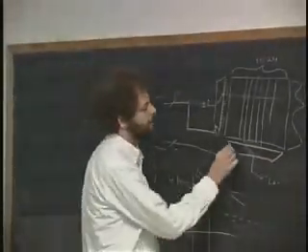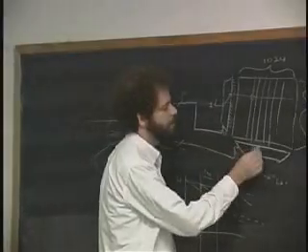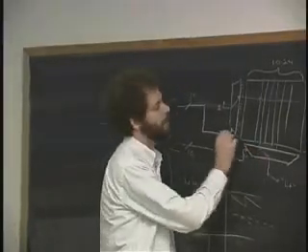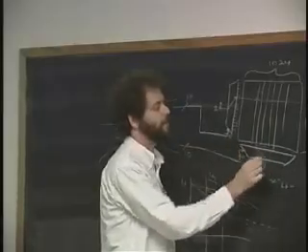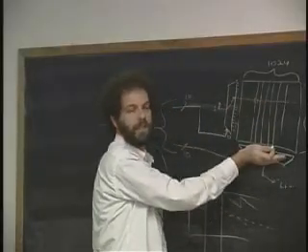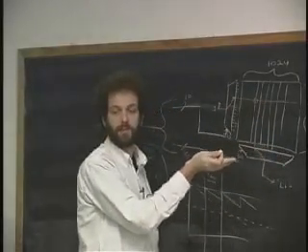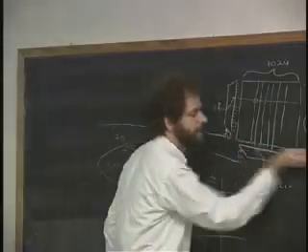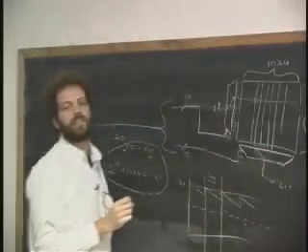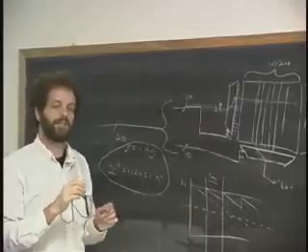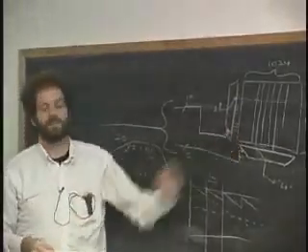Okay? Turns out that instead of doing this, which only grabs 1 bit at a time, if you want 1,000 bits, you can get out the 1,000 much faster by doing one transfer, and then in assembly line fashion, like we talked about the last time, you get zip, you get them all out. And so that's why SDRAM is so much faster than plain DRAM, which is the way that this thing works. But for now, let's just talk about DRAM.